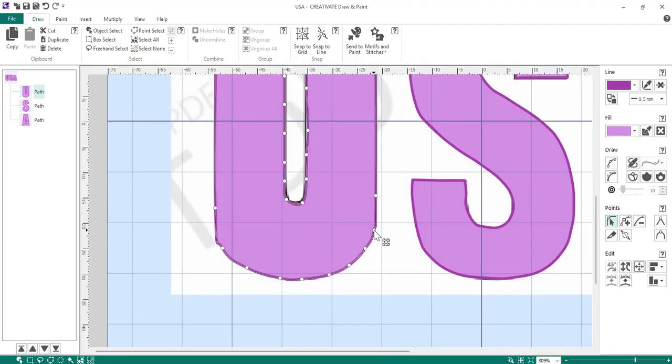Now, this is an excellent time to get into Bezier curves. So I am going to convert right here. Nope, that's join. Sorry. Here it is. Right here. Convert to Bezier line. And when I do that, you see all these little extra, these are rotating handles. I'm just going to rotate them, and this is what smooths out your lines.